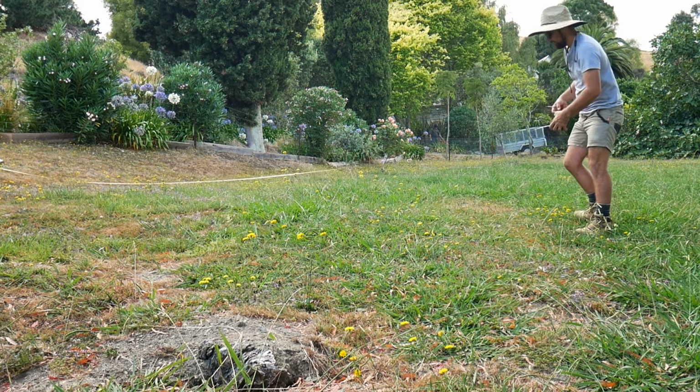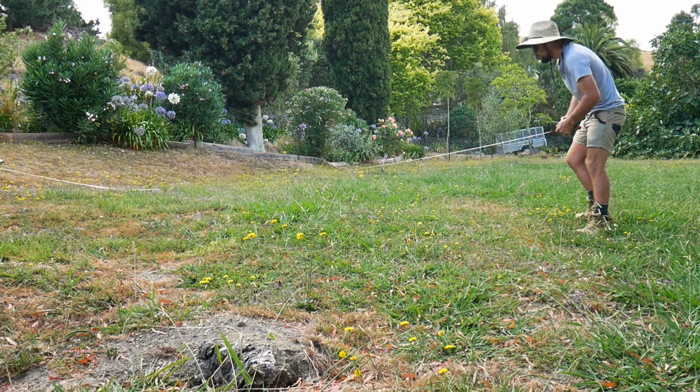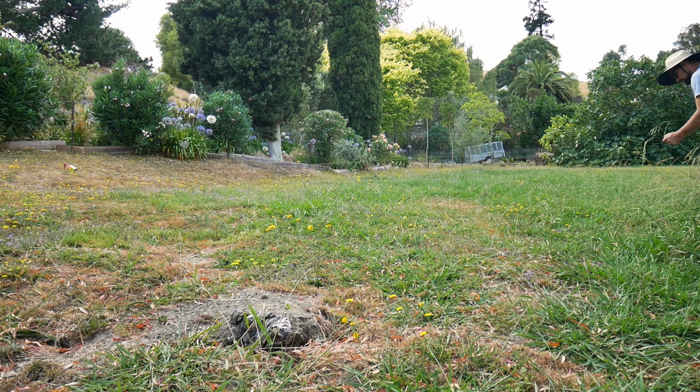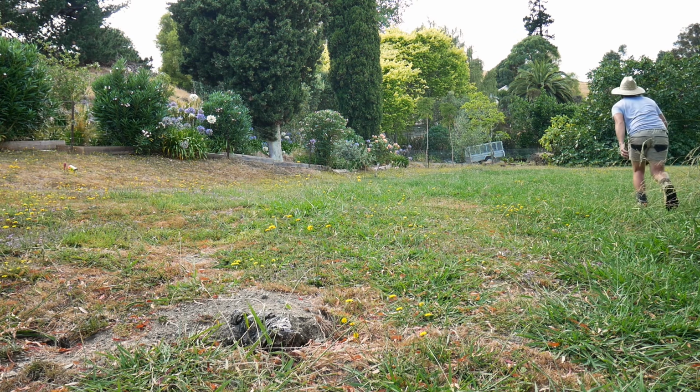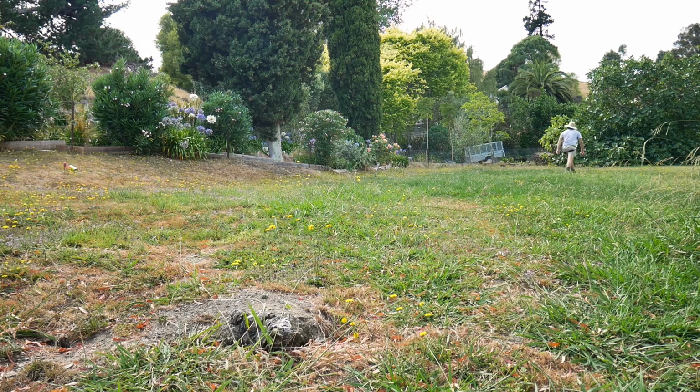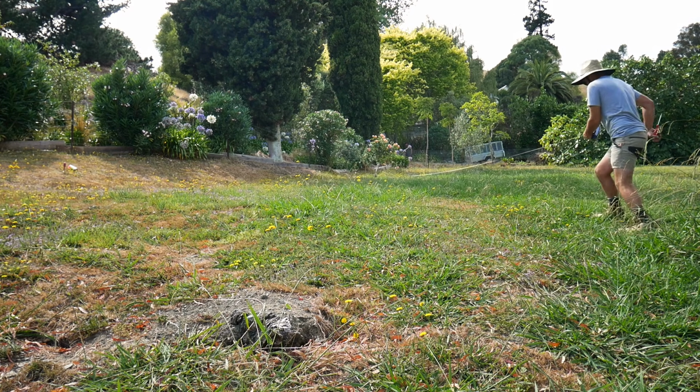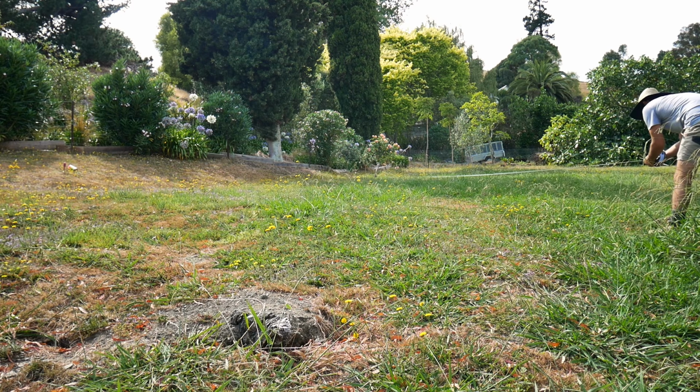There is a hidden trap here. I need to adjust my measurements for the slope. Due to basic geometry, those measurements actually need to be longer. If you're familiar with Pythagoras, you'll know that the right angle triangle has a longer side, the hypotenuse. On a sloping site, that longer side is the ground itself, while the dimensions on the plan only show the flat horizontal distances.